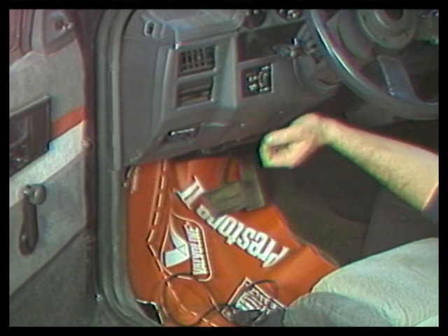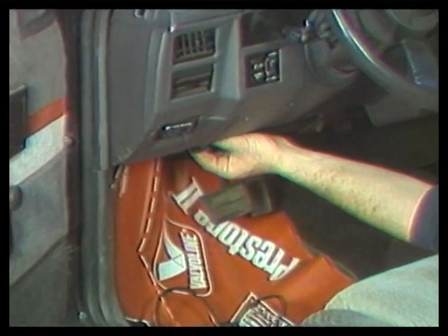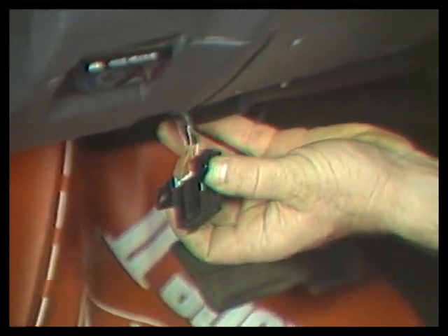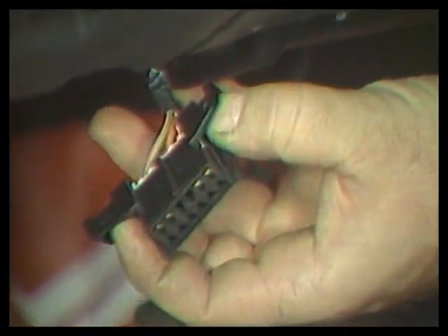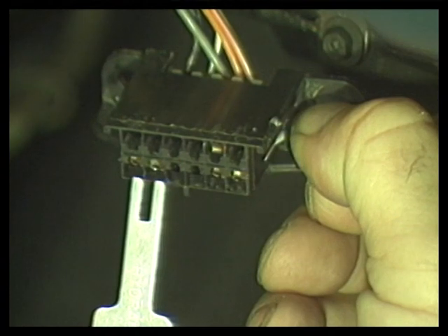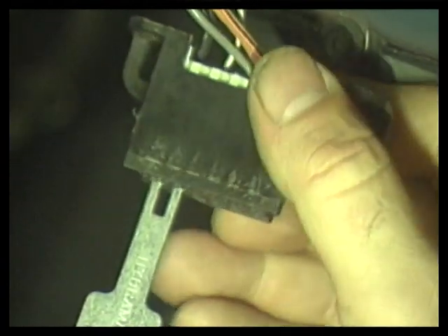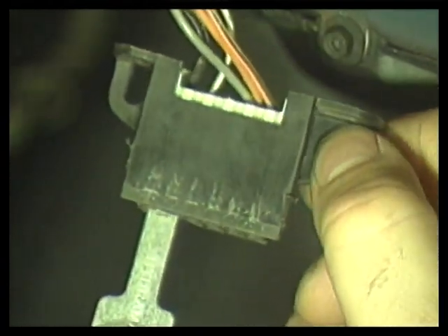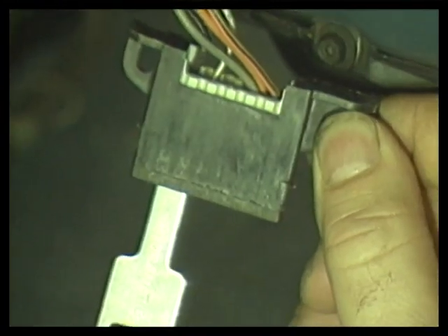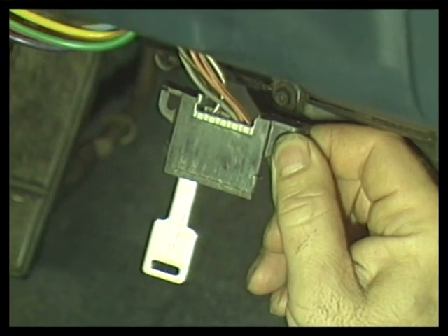If you are working on an older computer-controlled vehicle, you should be familiar with the ways to activate Computer Onboard Diagnosis to pull out trouble codes without using a scan tool. With GM vehicles, connect a jumper wire or clip to ground diagnostic connector terminals. Normally, connect the jumper between terminals A and B as shown.